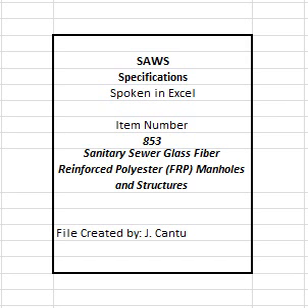The ring and cover shall be of ductile iron construction. The cover shall be solid with no vent or pick holes, hinged with underlying special hinge area leakage protection, the cover secured with 4 stainless steel bolts, and shall have a recessed pick bar for cover opening. Camlock type covers shall not be allowed.